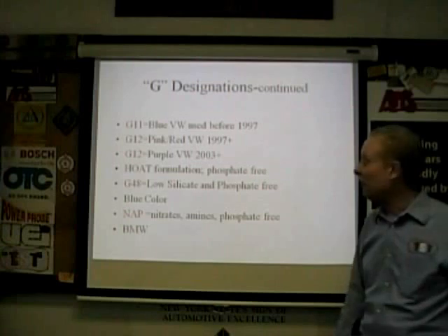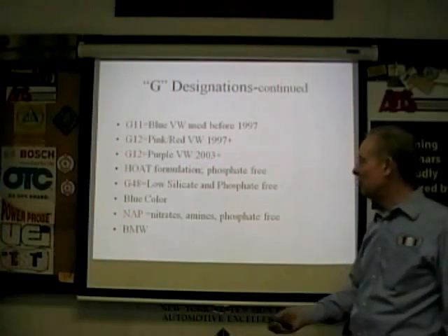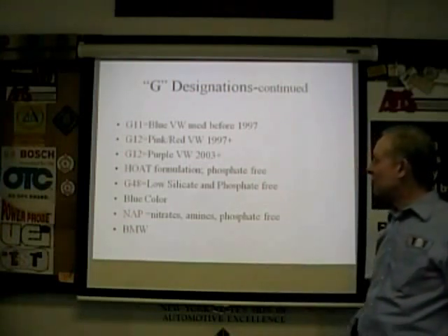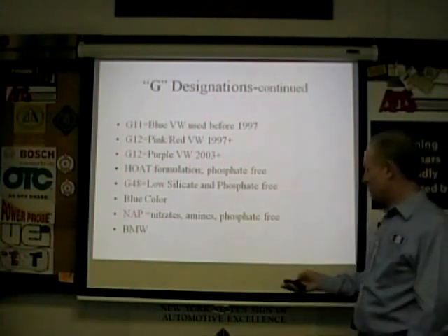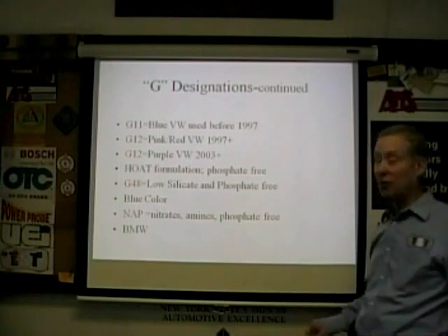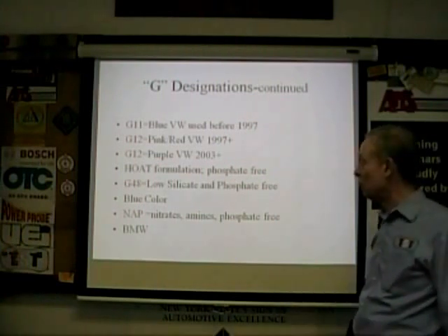G48, low silicate and phosphate free. It's blue in color. Nitrite, again, these chemistries, you don't have to know the chemistries. What you have to know is the spec. BMW has their own spec. I've had very good luck with it over the years with distilled water.